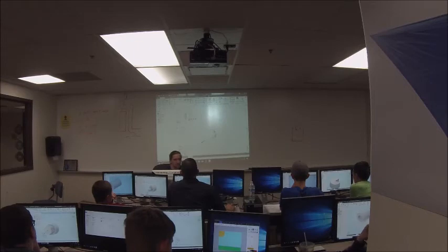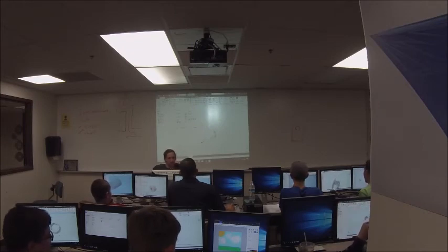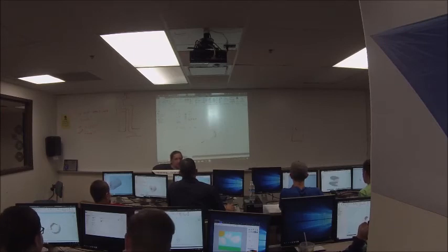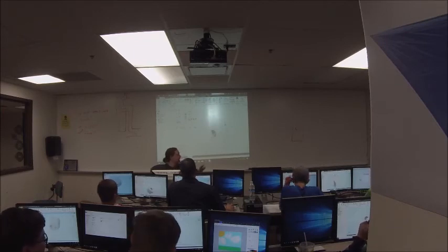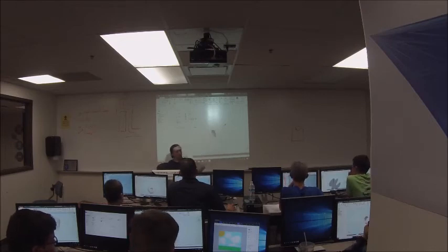So these buttons here, this one says join. This is what's selected by default. The button below it says cut. And there's also intersection, which I've never used, not once. It's kind of useful in certain cases, but I just never needed to use it. So you can click cut, and you'll see the little arrow flips direction. This part turns red, and it starts showing you that it's going to cut material.